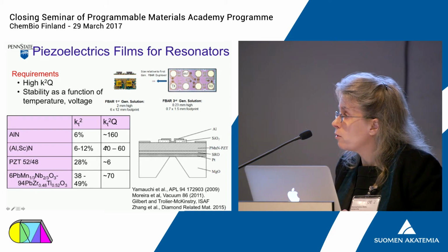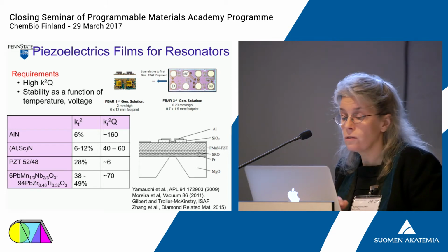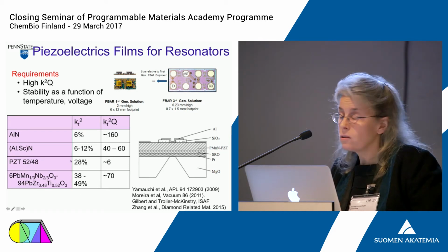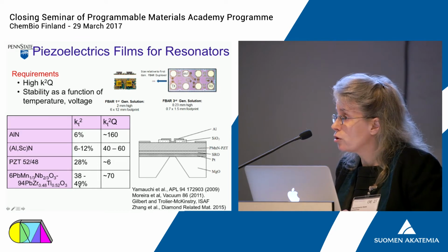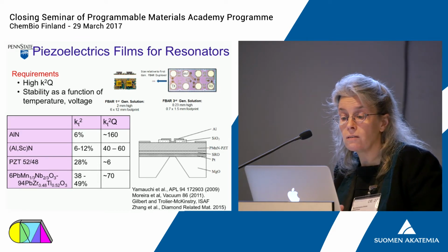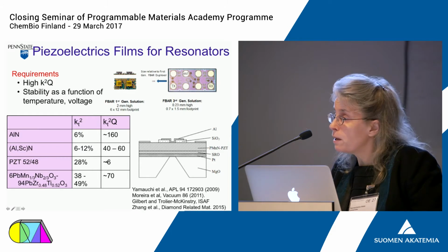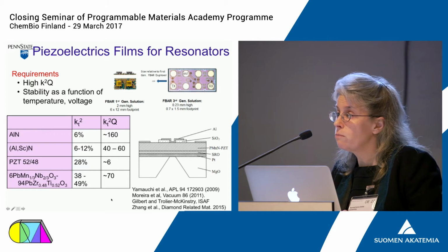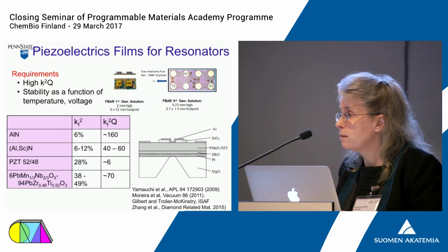Even though it has very, very modest piezoelectric coefficients, we would be very much interested in replacing this material with a ferroelectric solid because the coupling coefficients are much larger, they can make much broader bandwidth devices, but at present we still pay a penalty in the mechanical quality factor because domain wall motion is dissipative.